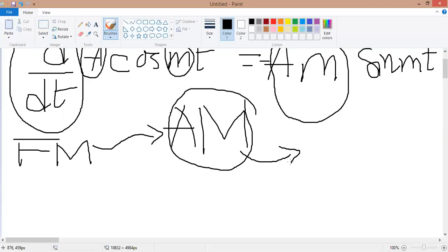It is also possible through other methods, such as two levels of product modulator, after which two levels of filtering action may be taken to obtain the demodulated message signal. These are the basic fundamental demodulation procedures that may be applied to obtain the message signal back from the AM signal.